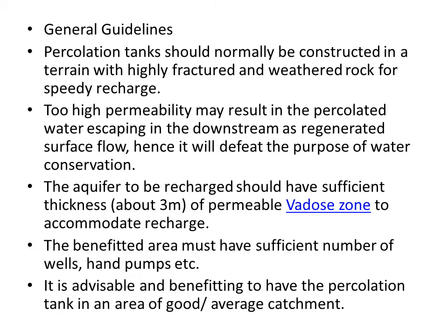So the percolation tank should normally be constructed on strata with highly fractured and weathered rock for speedy recharge, but it should not be too permeable. If it is too permeable, then the water will escape downstream as a regenerated surface flow, which will defeat the purpose of conservation.